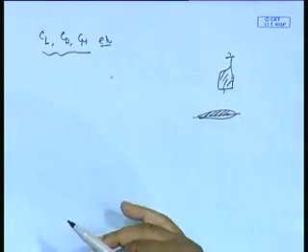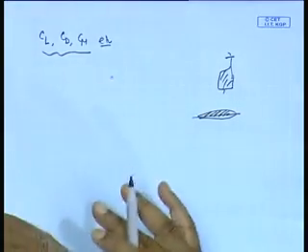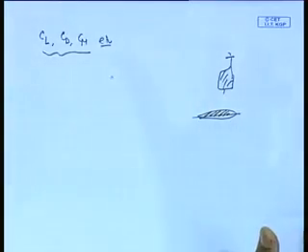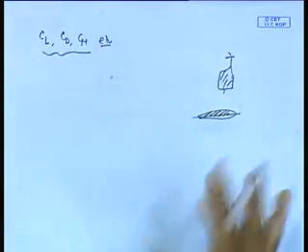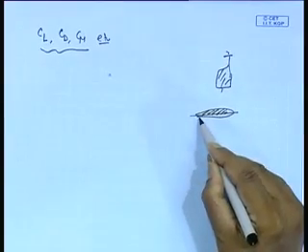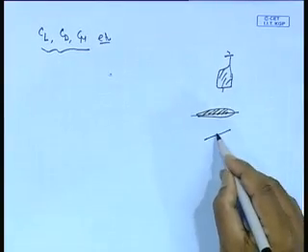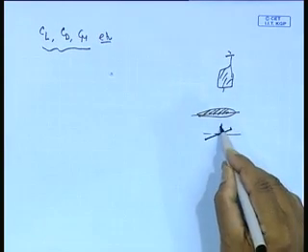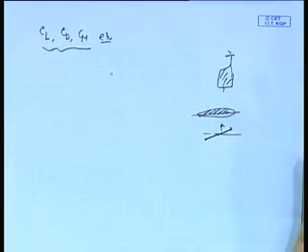So later formulas all realize that you will get much better rudder performance if you use an aerofoil section of some form. If you take an aerofoil section, you get the benefit of the shape for lift and also angle of attack. Even with just a flat plate, if you look at angle of attack, you will get a lift, but not so much. And those formulas are based on a similar kind of idea.